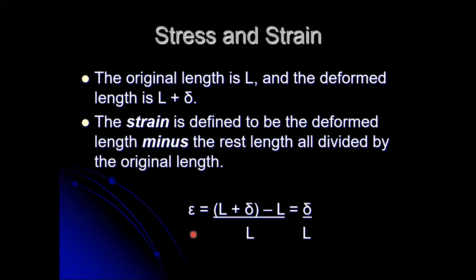So let's take a look at a couple examples of strain. So strain is all about length and deformation. It doesn't calculate directly from force or from stress. Stress doesn't really factor in here. We're going to see in a moment that there's a connection between stress and strain, and there's a proportionality there. The more stress you have, the more strain you get. But as far as calculating it goes, you don't have to do anything but length measurements to calculate strain. So let's take a look at that here.